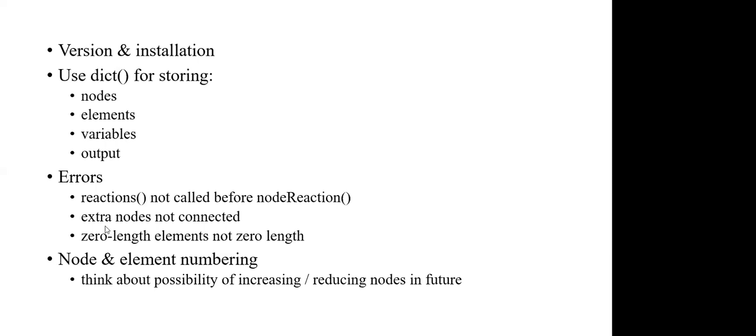Sometimes I have some extra nodes defined which are not connected, and it gives me errors. So just make sure that you have all the nodes connected, and you don't have a node flying outside of the model.